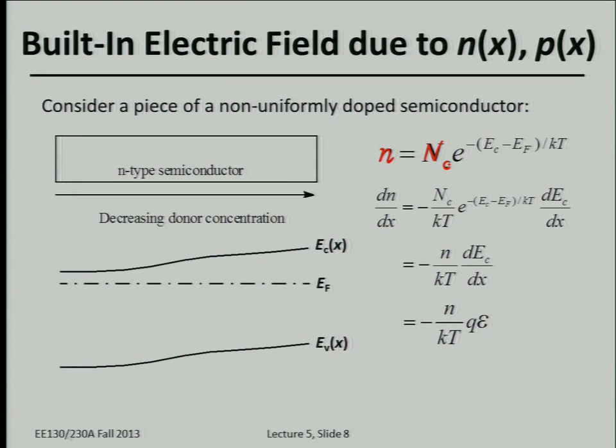I also want to talk about how to memorize this relationship. No matter how highly you dope the semiconductor into N-type, n should always be smaller than Nc. Nc is a very huge value; it's the limit of how many electrons you can occupy around the bottom of the conduction band. So n should always be smaller than Nc, which is why there is a negative sign here. Also, Ec is always higher than Ef in energy space, so Ef should always be lower than Ec. So this is positive and this should be negative, to balance the relative values.